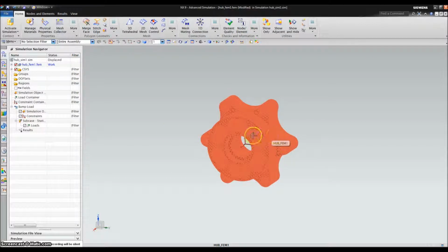Every time it selects this thing, it's going to individually select every node, and then individually select every connection between every node, and then individually select every element. And then when you mouse over, it's going to undo all of that in backwards order. And it does that element by element. So for those of you with slower graphics cards or connecting via remote desktop, that's going to be very difficult. So try to avoid doing that because it's just going to be a frustration.